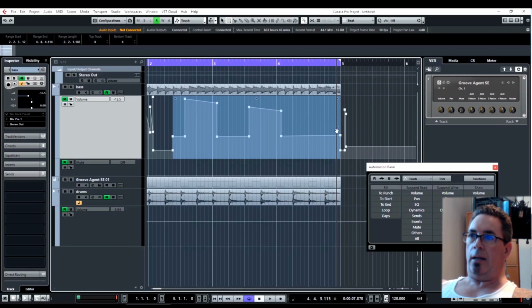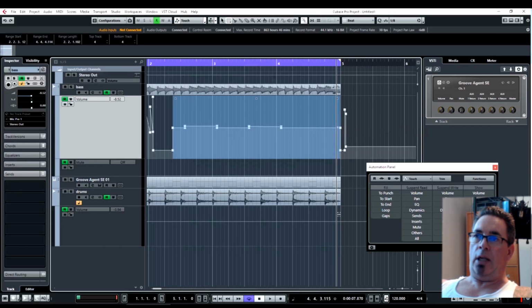Along with that, if you go to the middle on the right side, you have scale around absolute center. So this midpoint is absolute center. If I click there and hold and drag down, it's going to compress everything to that center point. If you drag up, now you're expanding, so creating a larger difference.